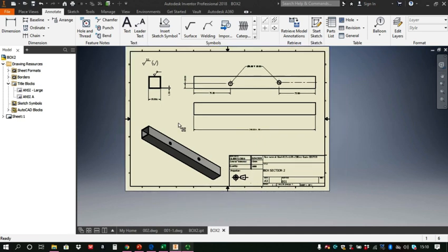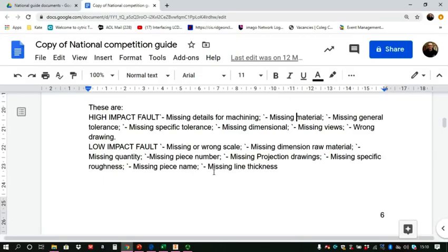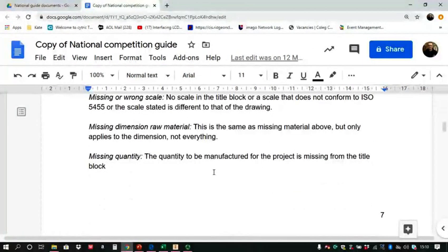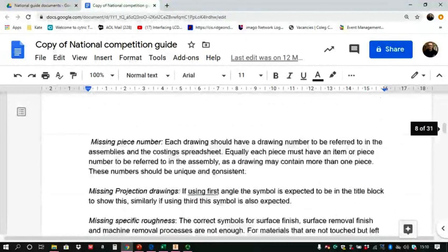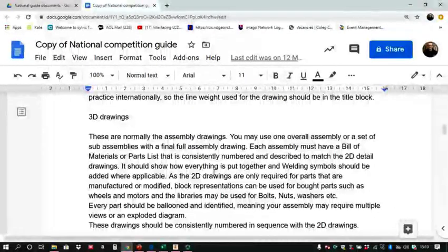3D drawings are pretty much similar, and just to take you through what we're looking for on the list, we are looking for a similar or same text box. We are looking for all of the things that were there in that drawing to be correct, as in, is it the right part number? Is it the right part description? We're looking for sequential non-repeated numbers in your drawings.